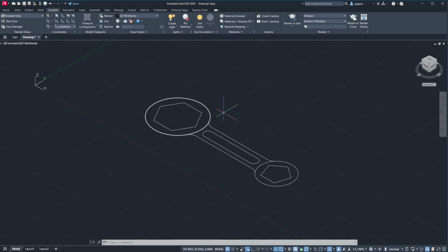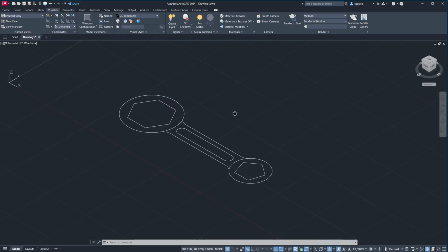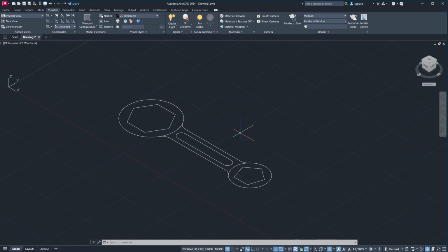No, it's actually in parallel already. Okay, that's fine. But in case you are in perspective mode, you can change it through this command. If you click this drop-down menu, it shows parallel, perspective, with ortho faces. What we want is parallel, because that's like the isometric view.